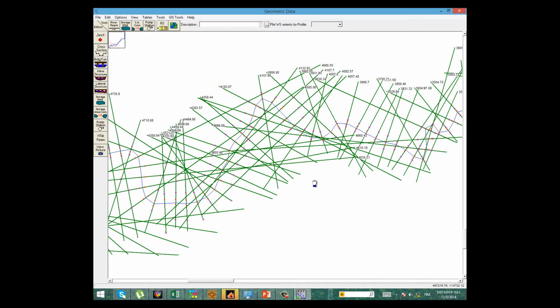So it's wrong to have the cross section of this one and this one by the side of this one, because HEC-RAS assumes that they are in the same plane, by the side of each other, and whenever the river becomes full, the overtopping flood may go to the other one.